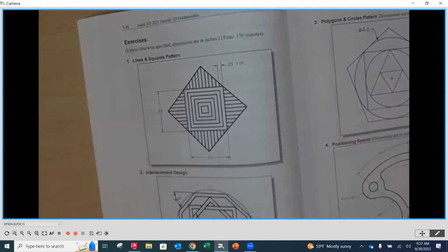Polygon. Yeah, we haven't done that one yet, but that's creating a shape and it's going to be like a polyline in the end. I'm actually going to demonstrate it so that you can see how that works. Polygon is going to be one. I heard something else. I heard offset, right? Offset is going to be another one. I'm in the chat. We've got a chat going. Offset, copy. Yes. Copy, offset, absolutely. So you're already devising your plan. As with anything else, there are multiple ways. I'm seeing another one. Mirror. Yes, we are going to use mirror.